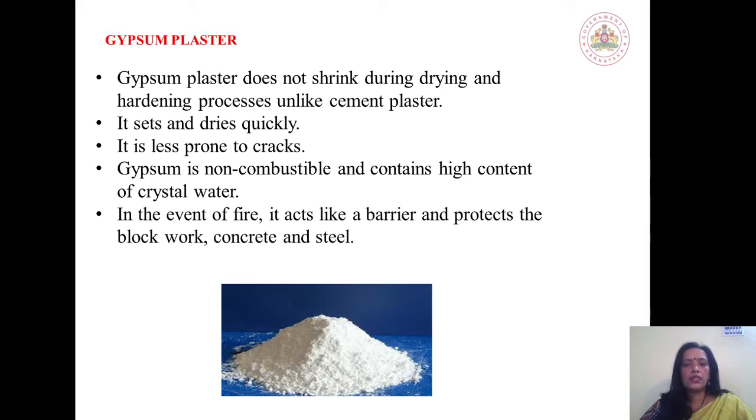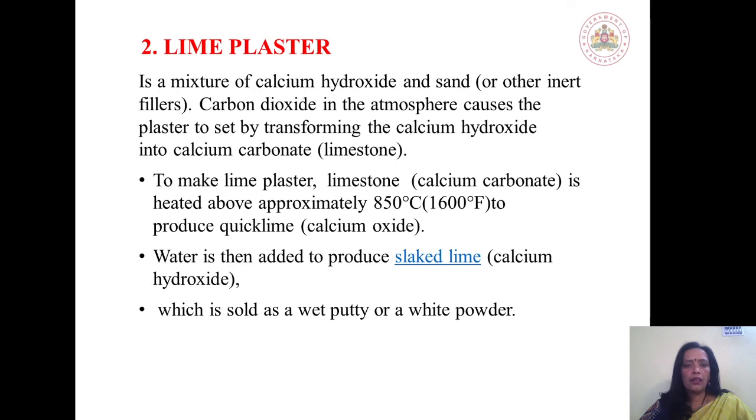Gypsum is not combustible and it contains a high content of crystalline water, hence it is fire resistant. It acts like a barrier and protects block work, concrete work and steel work. The picture shows the gypsum plaster. After discussing the gypsum plaster, the next classification of plaster is lime plaster.